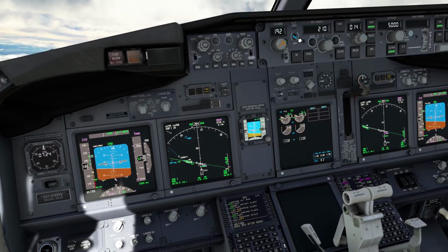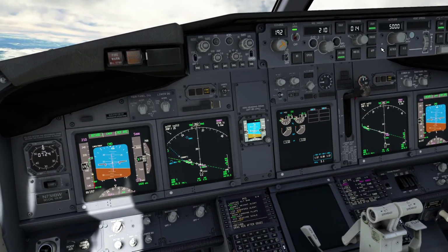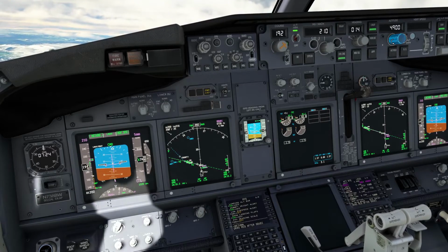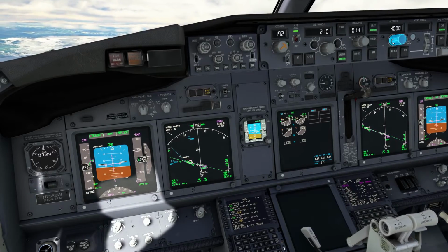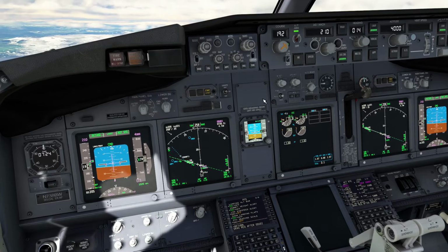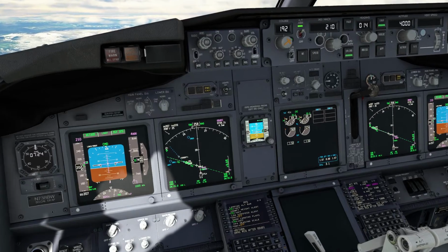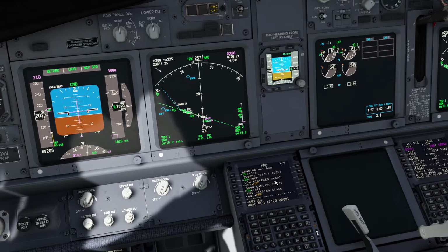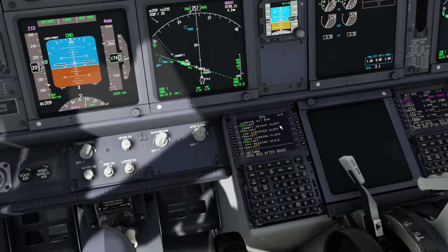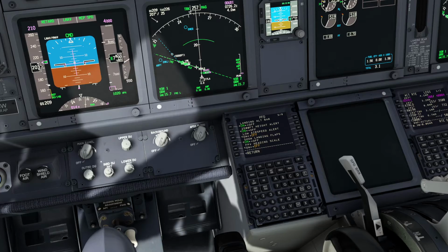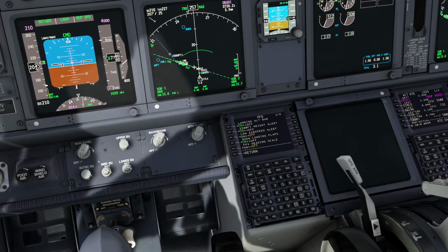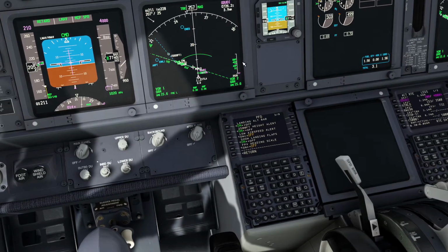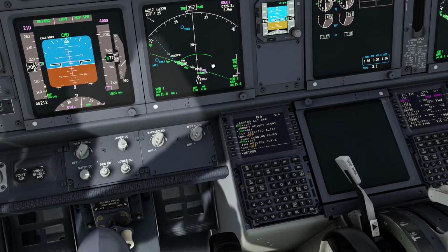Okay, now I'm engaging auto throttle. I'm going to use level change, and we are going to descend to 4,000 feet. Okay, so 4,000 feet. And as we are approaching the final fix, one thing that I'm going to do, I'm going to stop this airplane at this current position again. So we have the position freeze, so the airplane is descending to 4,000 right here.